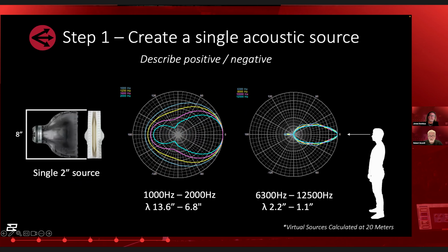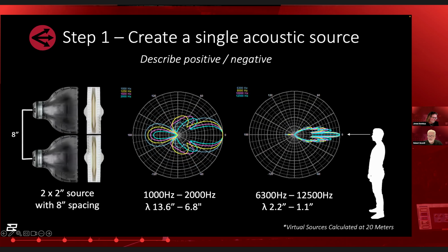Now, keep in mind that we put these on these isophasic horns and we've declined the overlap here. We've taken away any ability to overlap for the most part. I mean, these are 10-degree horns, 10, 12-degree horns, something like that. But we have achieved the initial goal, which was to get all the frequency, at full bandwidth, to exit this thing in phase, isophasic, right? Which we achieve with that unit. But as we start to stack it and add more components, that's where the trouble starts to head back our way.